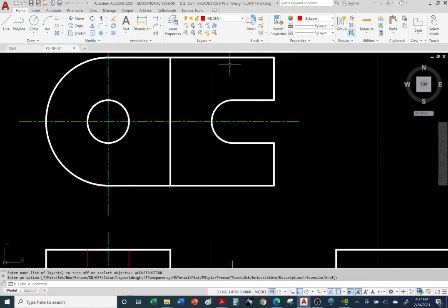Okay, so I deleted my center line here, or vertical center mark. Let me go ahead and bring it back in. Okay, so let's go to center layer, use the line command. All right, so you can see I have object snap on and I have ortho mode on, right? So I can track the center, go slightly beyond, click.